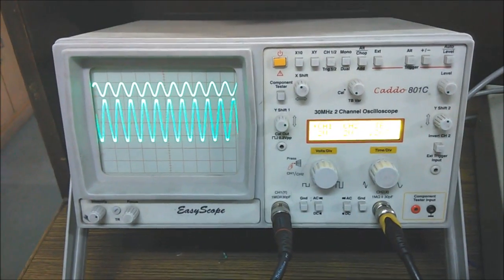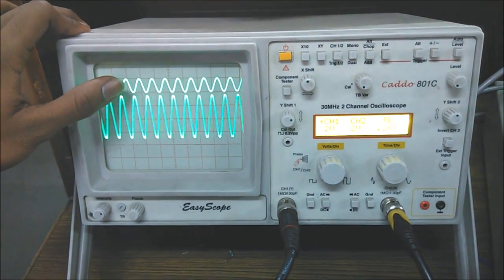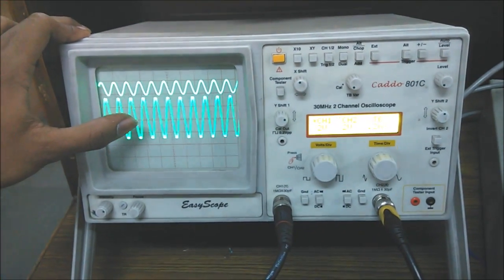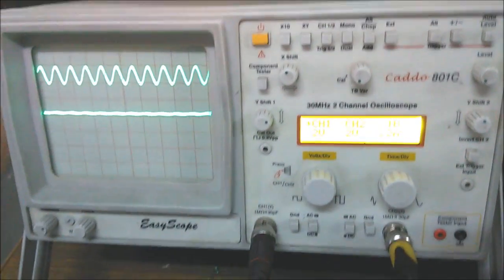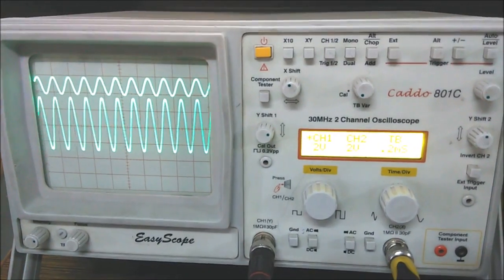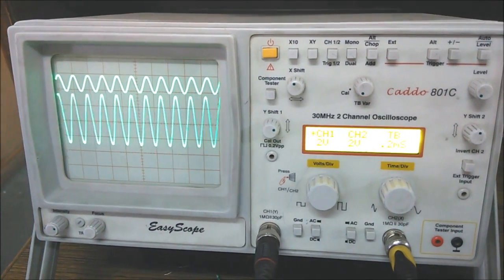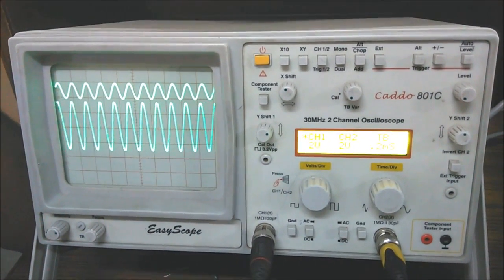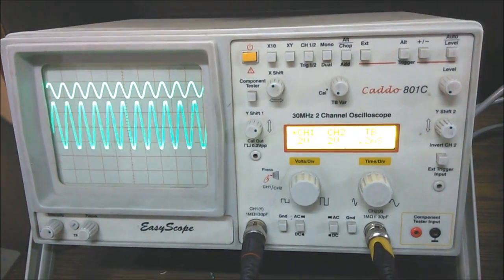Now we switch on the power supply, and we can clearly see on the CRO there are two waveforms. The top waveform is the input waveform, and the one below is the output waveform. You see the amplification on the screen, and it's a bit distorted because of the error we got in the connection, but still the output waveform is amplified. The amplification is possible because of the DC voltage that we connected to our op-amp and the circuit on the breadboard.